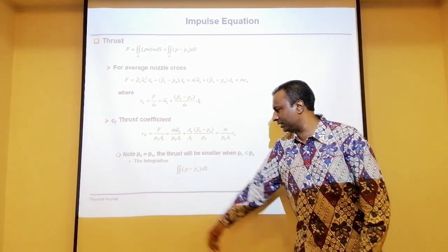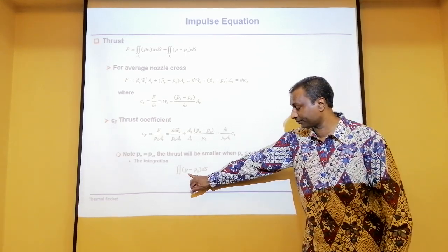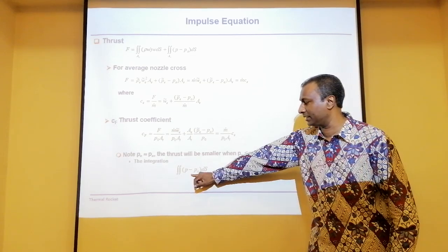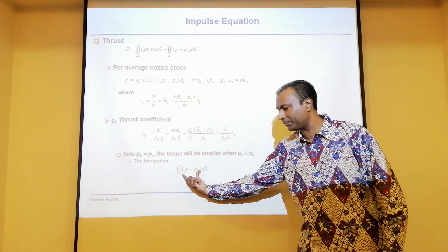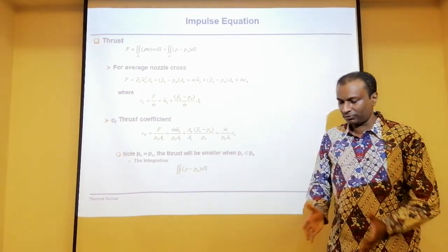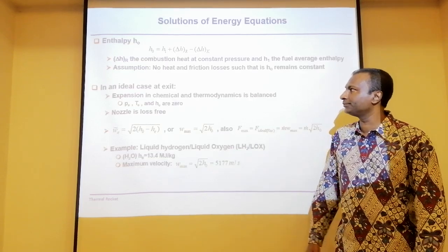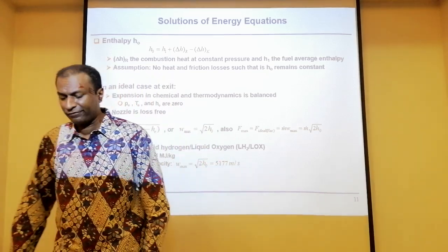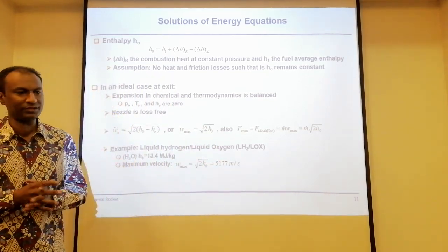Alright. If you do a double integration, basically we can practically find that exact thrust. Yeah? We can exactly find this one. This is going to be a delta P, in fact, delta P with respect to the exact surface. Alright, go on. I have also, in chapter 2, discussed how basically to look at the exhaust efficiency.